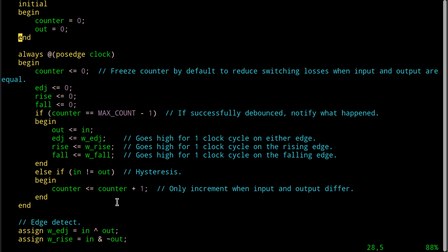This doesn't actually have a reset signal in it at all, which is maybe not the greatest thing, but probably okay, because we're just debouncing a switch, and this will happen without any reset logic, which would mean that the switch with debouncing logic runs all the time, whether the FPGA is in reset or not. Quite often you do want to see a reset signal come in, even if it's some trivial little thing here that doesn't really have a huge impact on everything else.